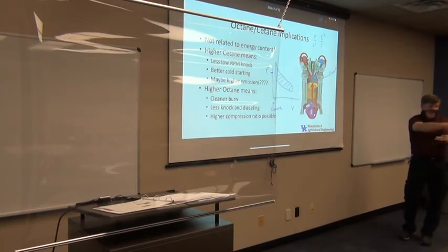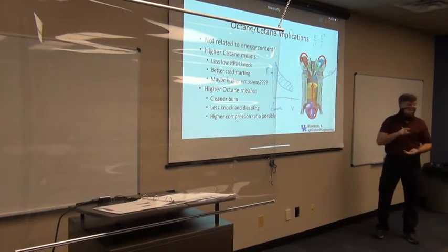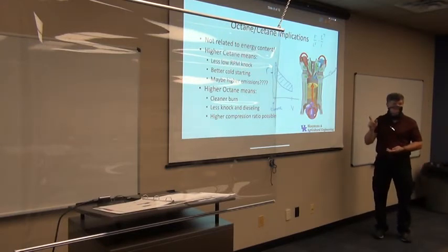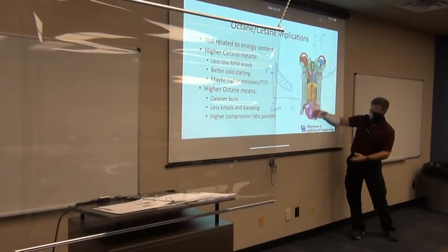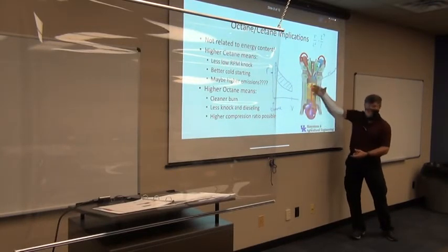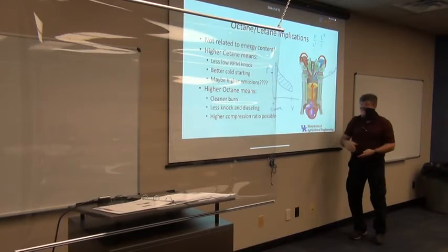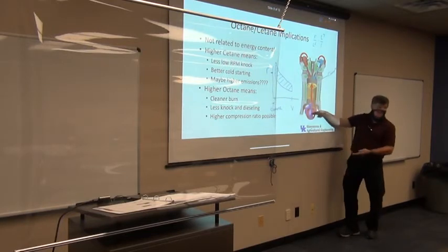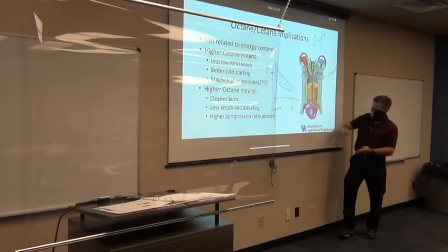There's less clearance volume. So I've reduced the clearance volume. Have I changed the displacement? No, the displacement is determined by the crankshaft down here and how far the piston is moving, right? So I haven't changed the displacement, but I have changed the clearance volume. And I've actually changed the maximum volume as well. When I pull this down all the way down, there's not quite as much volume up there, but I've made a small change there.